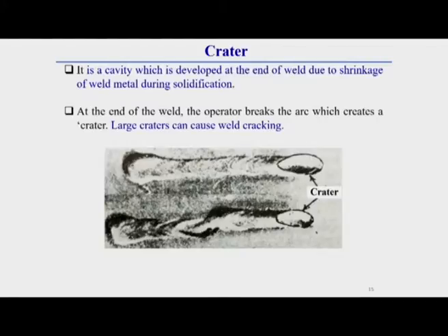So, first of all, in this welding operation, this has a significant effect and very frequently occurs. It is called crater. Crater is generally a cavity which is developed at the end of the weld due to shrinkage of weld metal during solidification. So, what is crater?